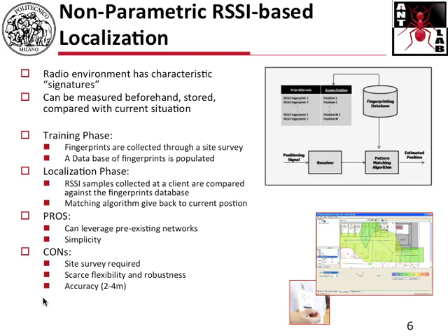Site survey is required, which means that this is basically a database-based localization system, which means that to run properly, you have to populate in advance a database of received signal indicator versus X and Y position. Okay? Which is costly, which means that you have to pay at least one person to go there and do these tests, hopefully with a high granularity, so a kind of every meter on a grid of 1 meter step at least, which is again a costly kind of procedure in terms of time and money.